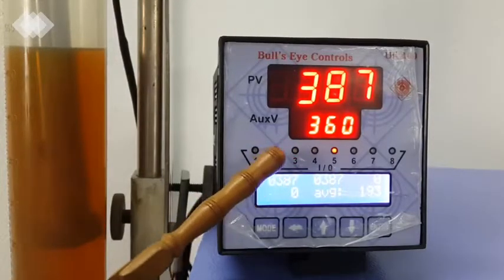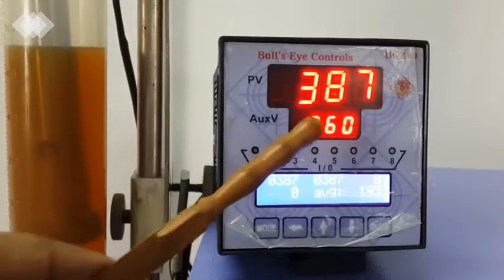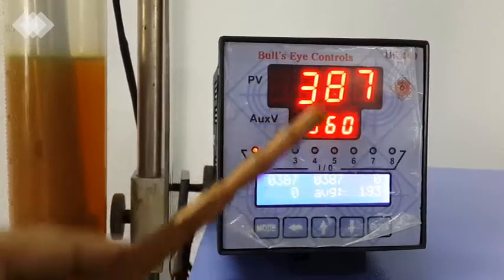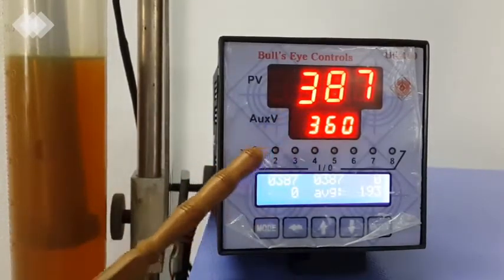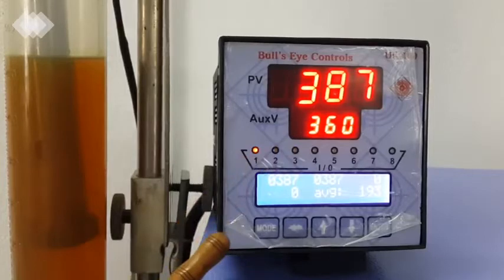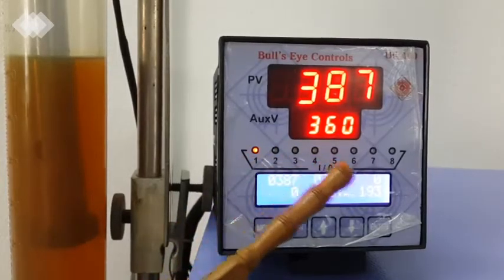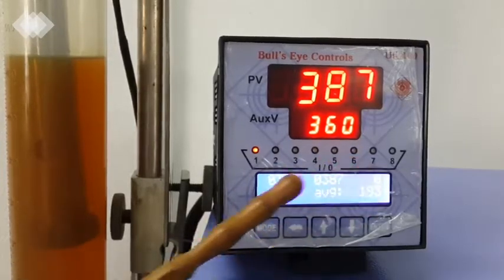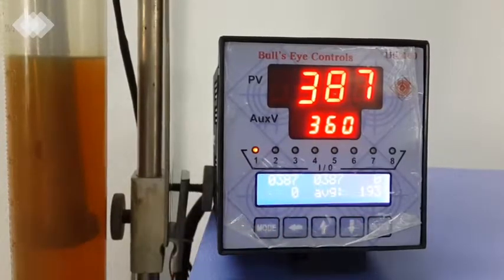Okay. See, we are showing you in this demonstration in an open loop condition. There is no solvent addition actually happening, so you can see that water will keep adding continuously. In fact, the addition signal will keep coming. Now there are only 2 readings yet, so the average is less. Once all the 4 readings are there, then it will start showing the correct values. So that's it, this is a brief working. We can observe 2 more readings and then we can close this chapter.